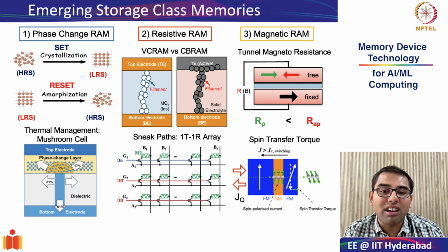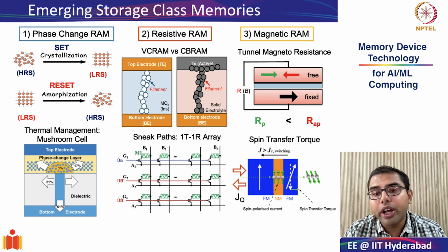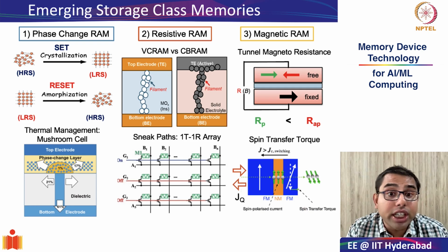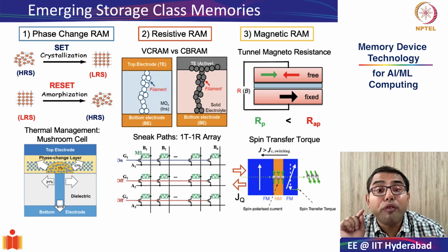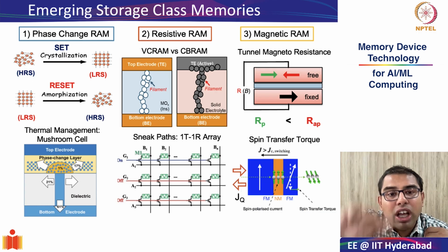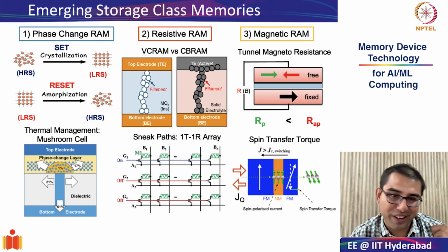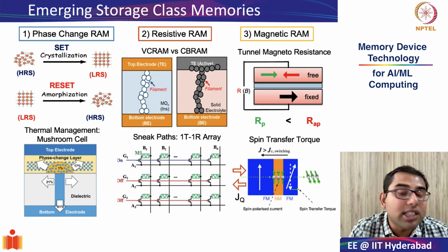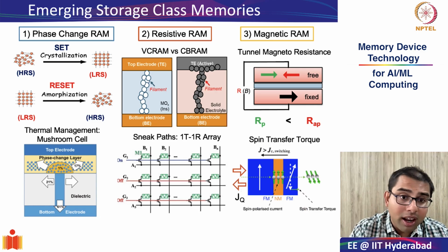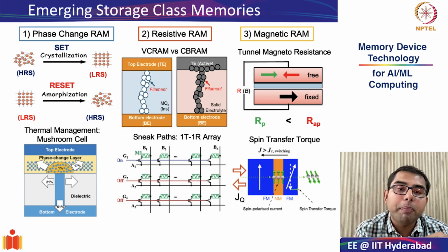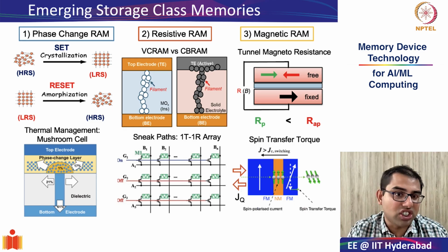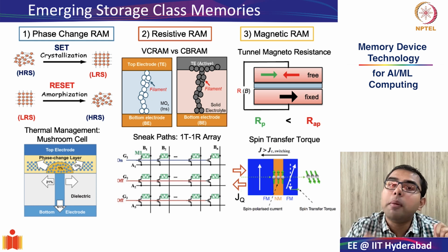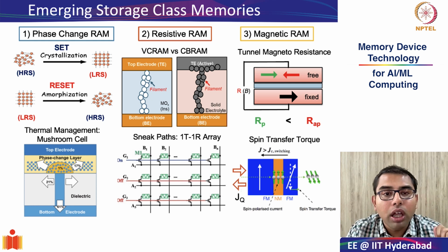This is a quantum mechanical concept where, depending on the relative magnetic polarization orientation between the free layer and the fixed layer, you can switch the device from parallel to anti-parallel configuration, where the parallel configuration had low resistance state. Remember the density of state argument that we gave, versus anti-parallel, which has high resistance state. And we saw several mechanisms of how you switch the polarization in the free layer.